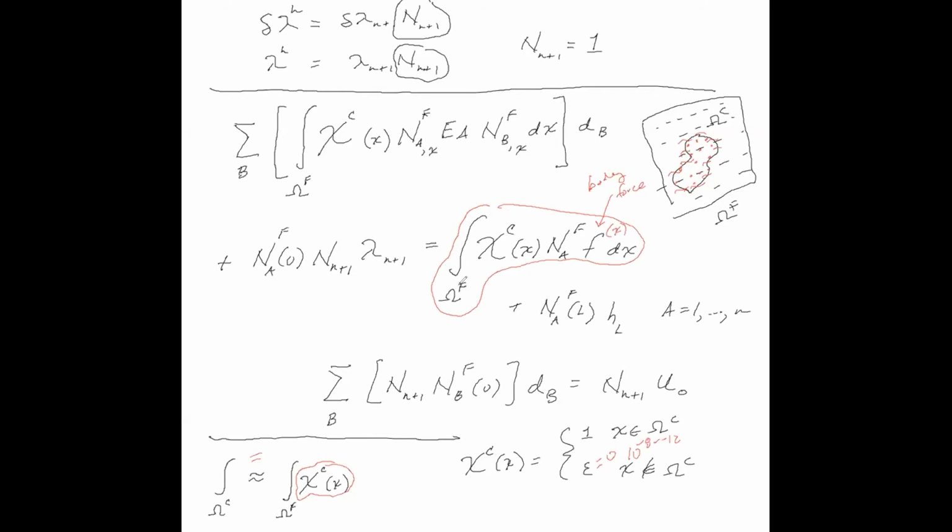What we're going to do is a change of variables. We'll pull this back to the parametric flex domain. I'll do this in a minute. Let me pull this out a little bit so I have a little more room. This will become F of X F of XC. So this F is defined over this domain in terms of physical coordinates. So you map your parametric coordinate into physical coordinates, and then you test and say, am I in the CAD geometry? And if so, you simply evaluate your function at that physical coordinate.